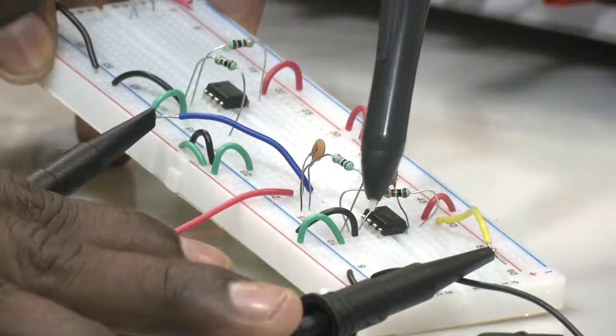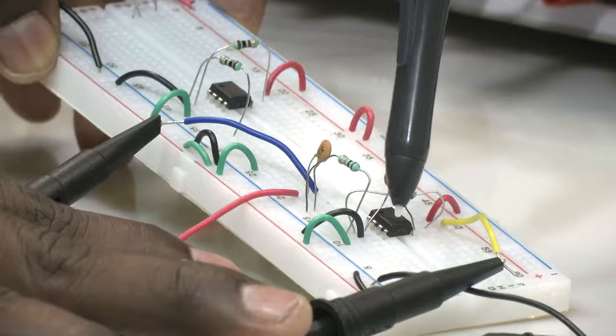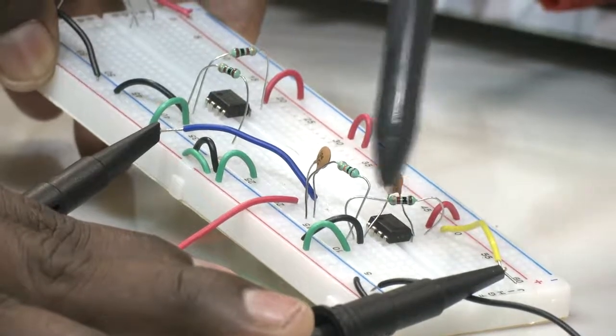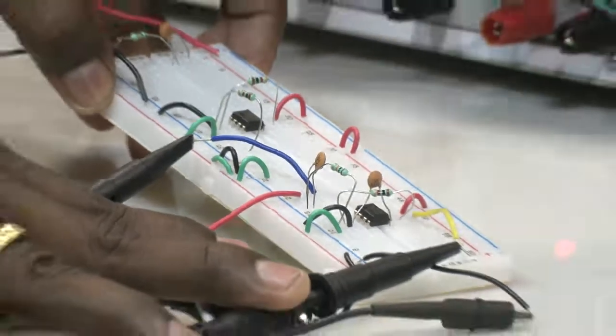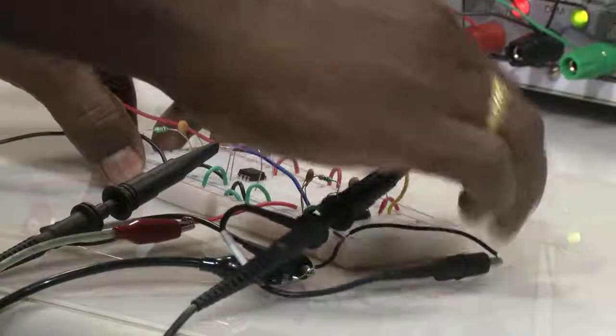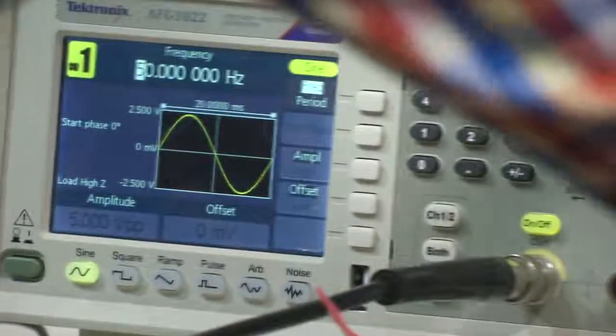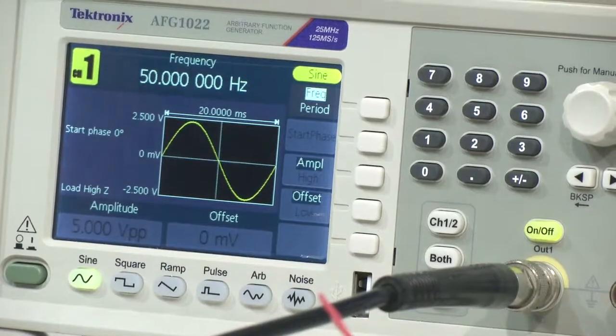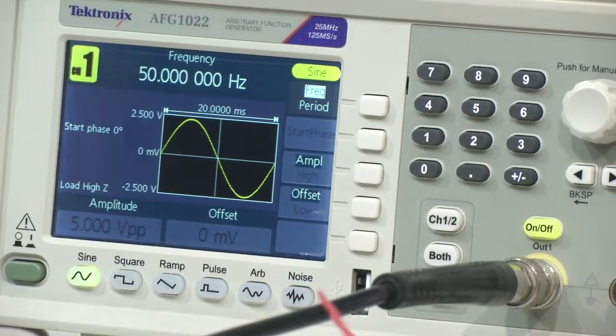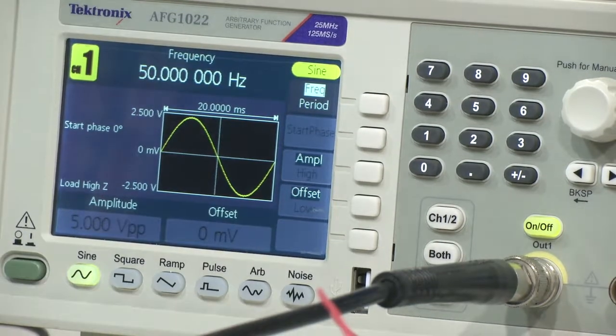The only change between passive and active is that here we have an op amp and we can change the gain, alright. So, let us apply the signal. Because the op amp is there, we are using the DC power supply. Through the DC power supply, we have already applied plus minus 15 volts as bias voltage. Now, if you see the screen, what do you observe?